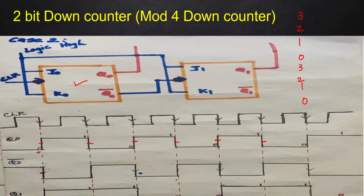This is the timing diagram of your Q0. You need to take the complement of this: wherever Q0 is low, you mark high, and if Q0 is high, you mark it as low. So just draw the complemented form of your Q0, that will be Q0 complement.